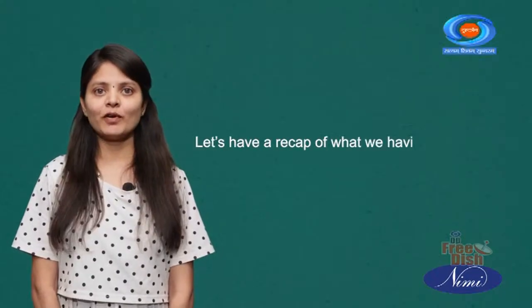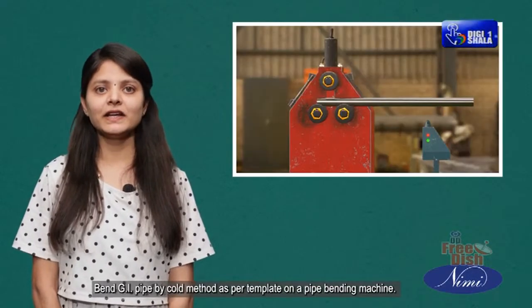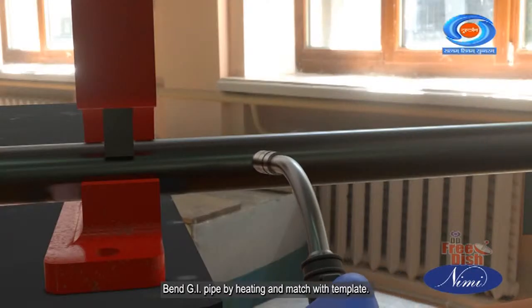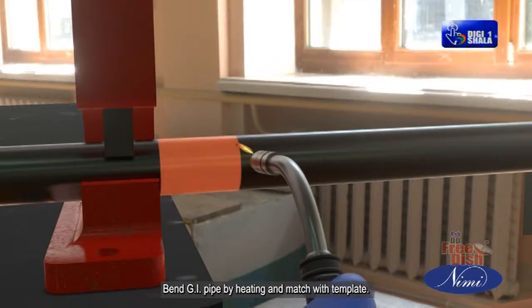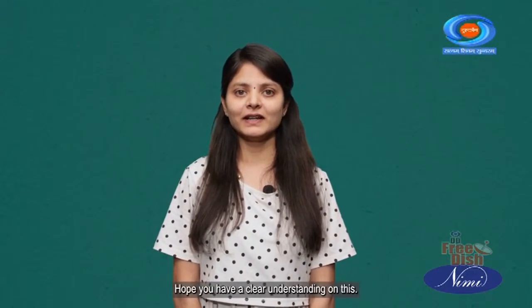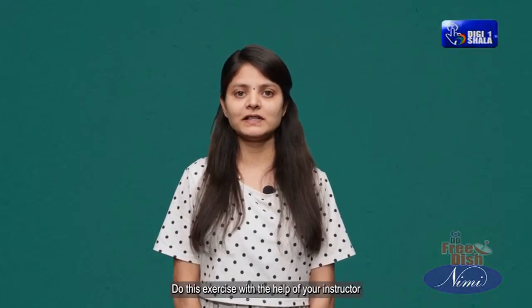Let's have a recap of what we have learned today. We have learned to bend GI pipe by coil method as per template on a pipe bending machine. Bend GI pipe by heating and match with template. Thus, we have learned how to bend pipes using hot and cold methods. Hope you have a clear understanding of this. Do this exercise with the help of your instructor.